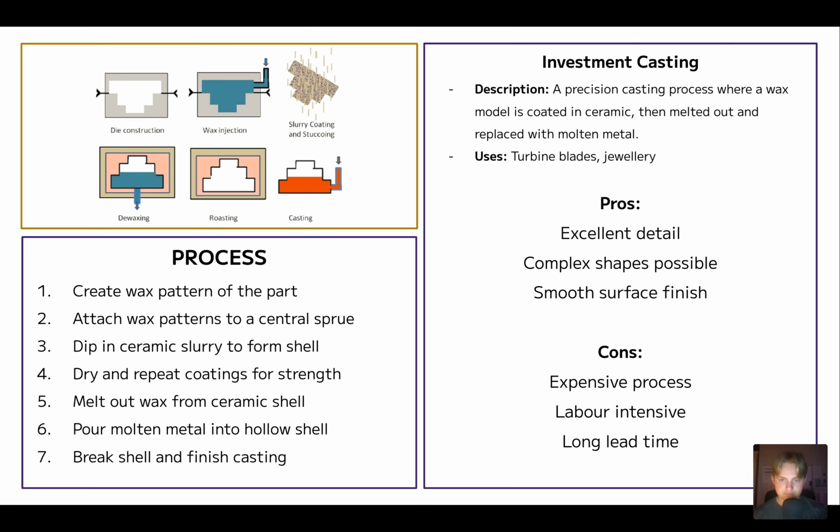And the pros of it is that it creates really excellent detail and allows us to have very complex shapes with a very smooth surface finish. So this is the best of both worlds. This is like your sand casting, which allows for that very complex shape, but also with the smooth finish that you don't get with sand casting.